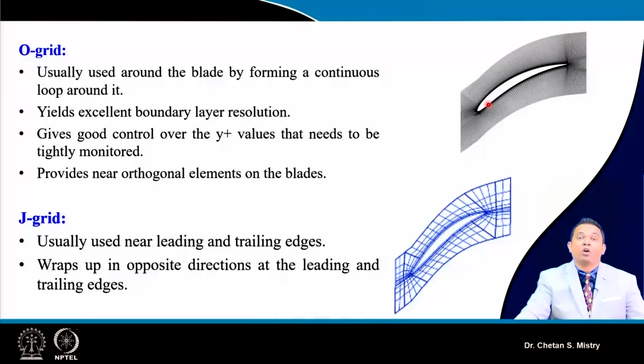Just understand what is happening on my suction surface and on my pressure surface. That is of our interest, because it represents the work-done capacity of each individual aerofoil. A blade comprises a number of such aerofoils, so for each aerofoil we need these details to be available.